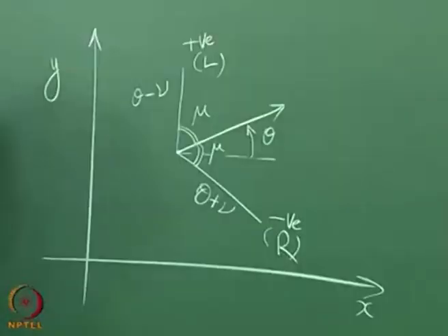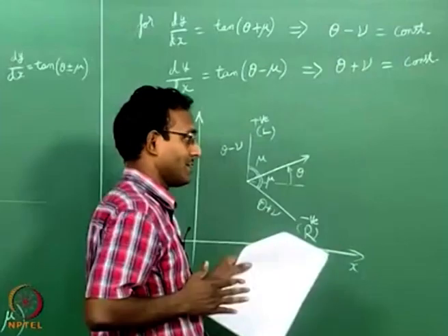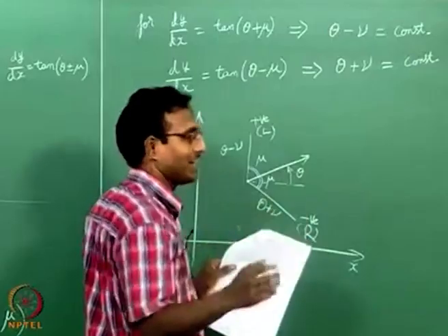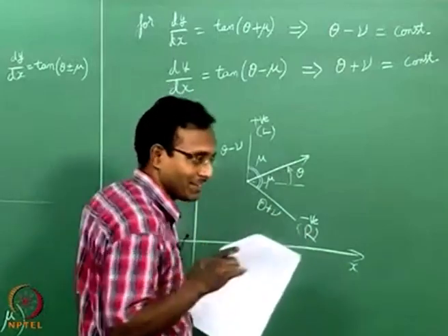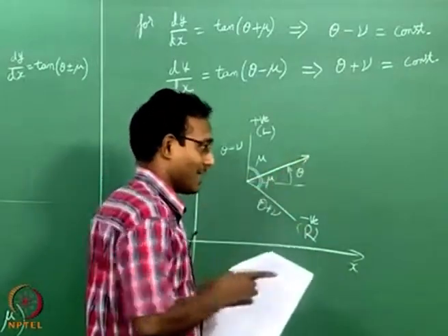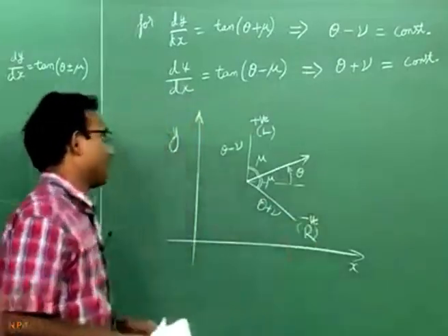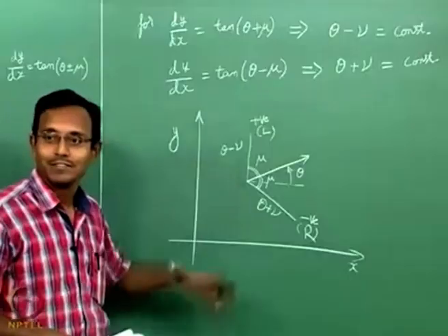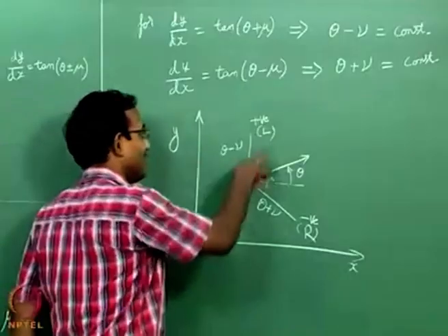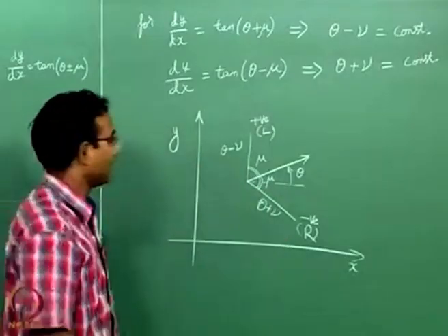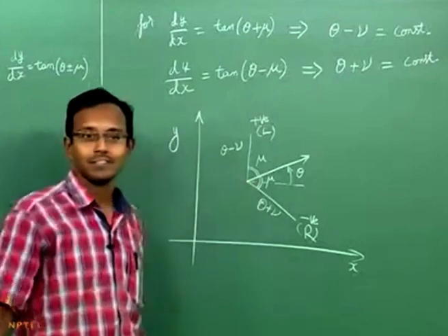That's another name given to it. That is, if I am the fluid element going like this, there is a wave that is running along. I didn't give you the word wave yet. There is a direction which goes to the right of me while I am moving straight like this, and there is another to the left of me going this way. If you are looking from the top, that's the picture you will see here. Okay. So that is what is written here. This is our right running and left running characteristic.